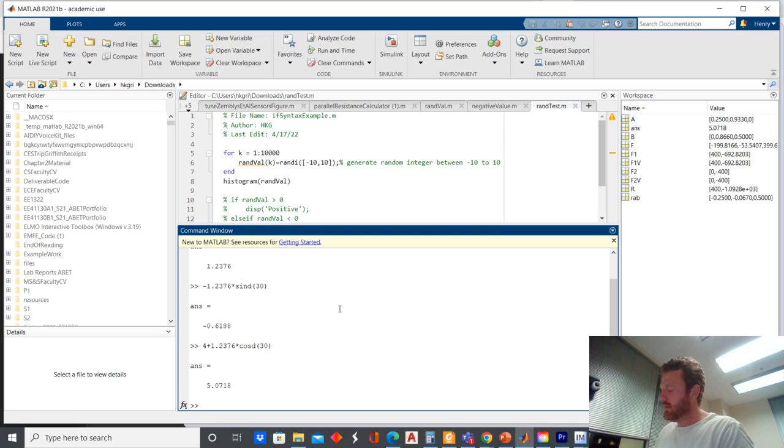Okay, so let's think for a minute what we know. We want mag B to be less than 7.7 kilonewtons, and mag A to be less than or equal to, up to, probably just less than. It's a little bit ambiguous, but we'll just say less than for now. You'll see it won't really matter in terms of our answer. But we know that the roller at A can support a load of up to 3.3 kilonewtons. So these are all, if you think about it, restrictions. These are restrictions for B, and we already have our restriction for A.